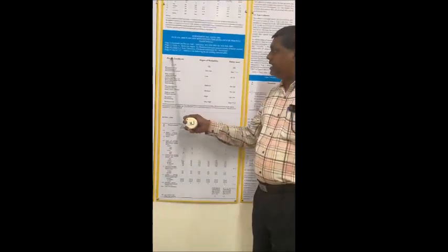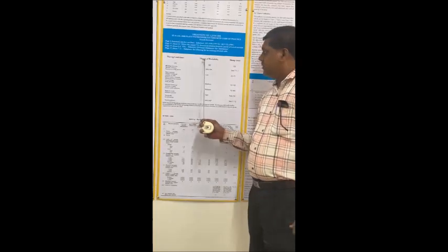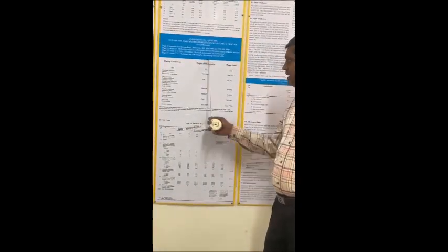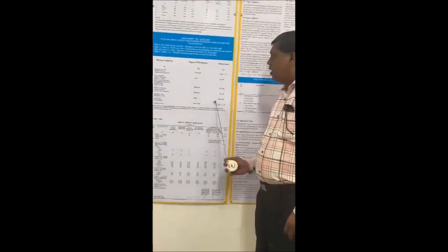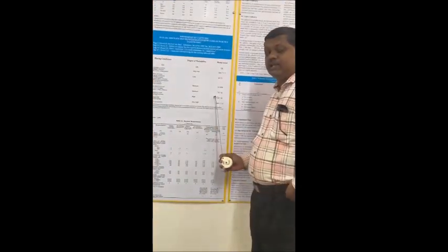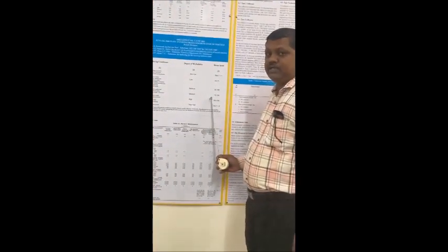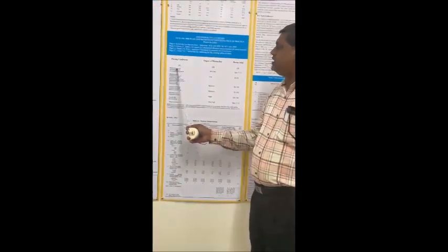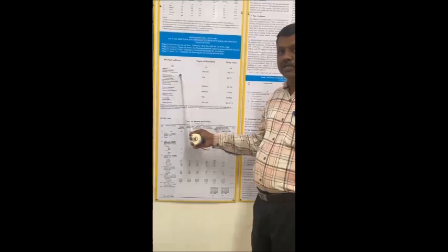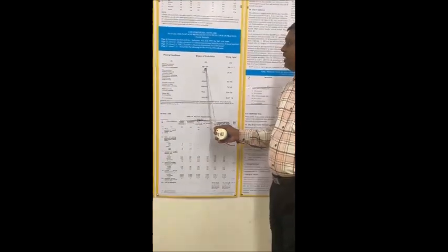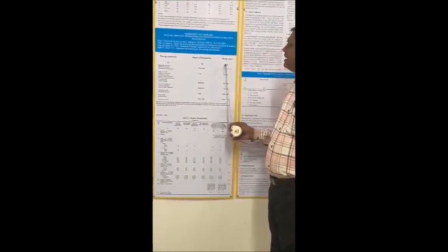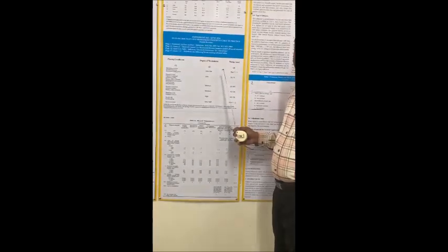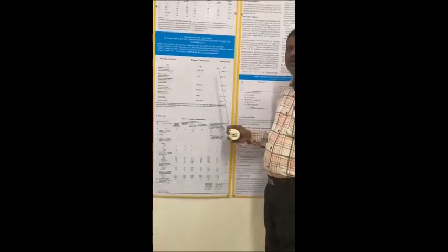So here the basic conditions are mentioned. The required degree of workability for that specific condition is explained in the second column, and in the third column the value of the slump required for the placing condition is explained. Now you can see here the placing conditions: blinding concrete, shallow sections, pavements using pavers. The degree of workability is very low and the slump is generally 0. For pavement concrete the slump is 0 because a harsh concrete is required for that placing condition.